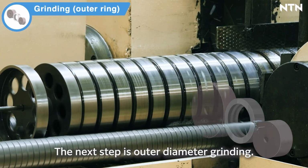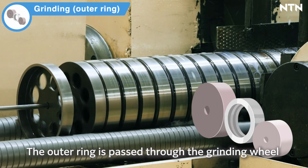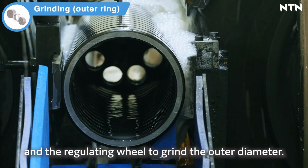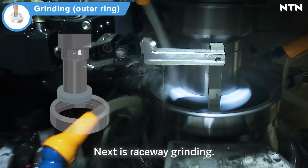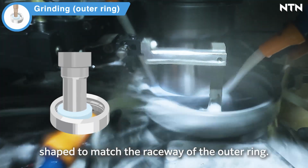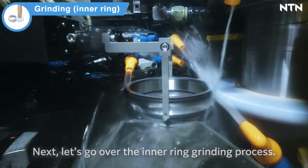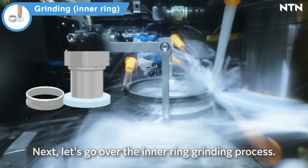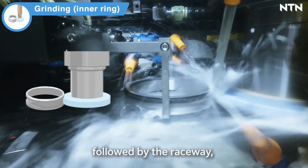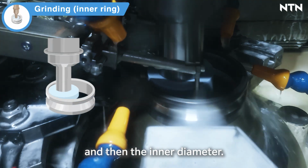The next step is outer diameter grinding. The outer ring is passed through the grinding wheel and the regulating wheel to grind the outer diameter. Next is raceway grinding. The outer ring is ground using a grinding wheel shaped to match the raceway of the outer ring. Next, let's go over the inner ring grinding process. Like the outer ring, the face is ground first, followed by the raceway, and then the inner diameter.